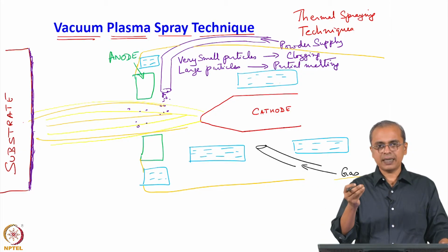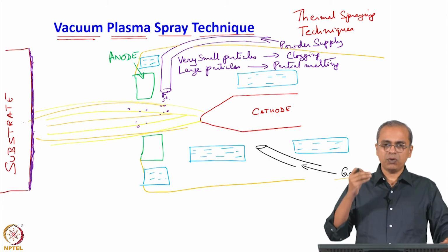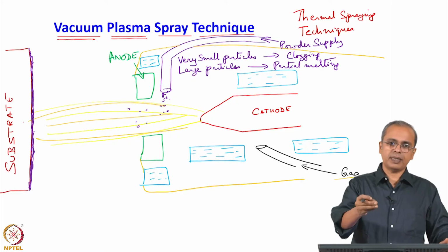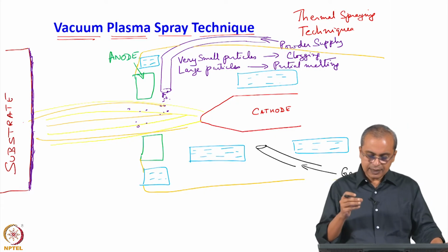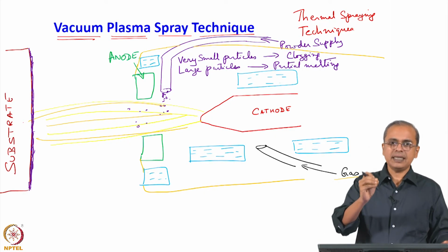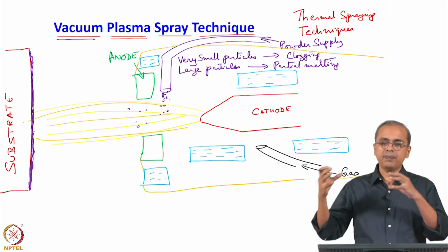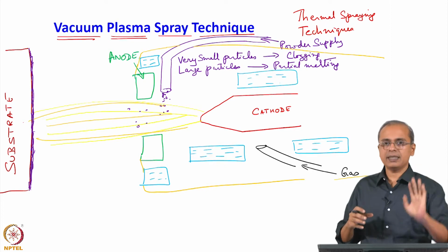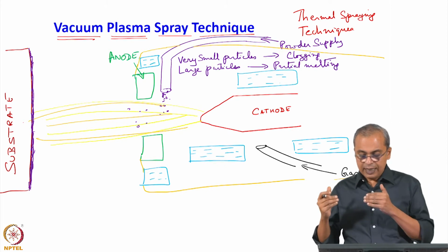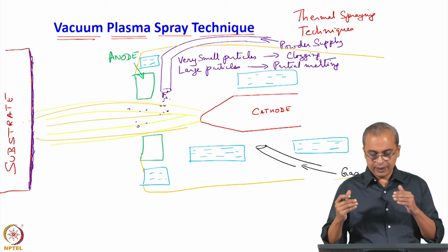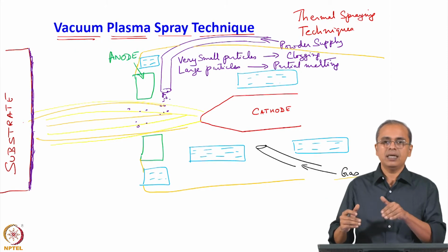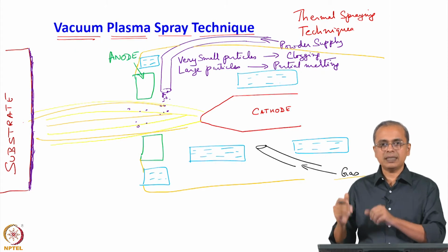The larger the particle, the more time heat takes to go from the surface of the particle to the center. So, the greater the time required for the heat to reach the center, you may not completely melt the particle, and even before that you will hit the target. And if you want to change the crystal size, you will not accomplish that with only a partially melted particle.